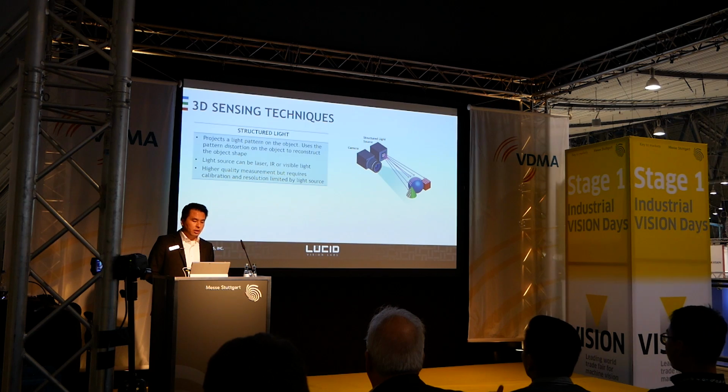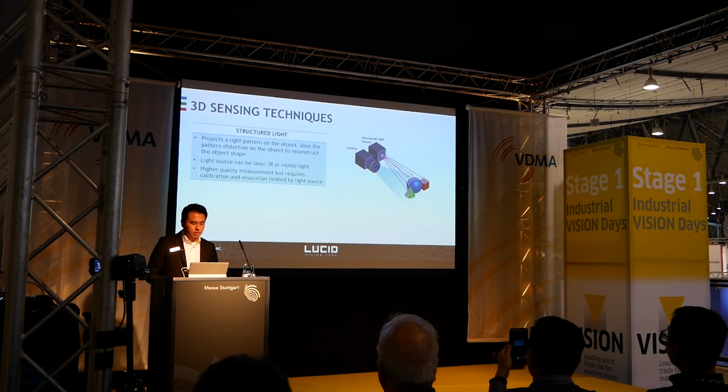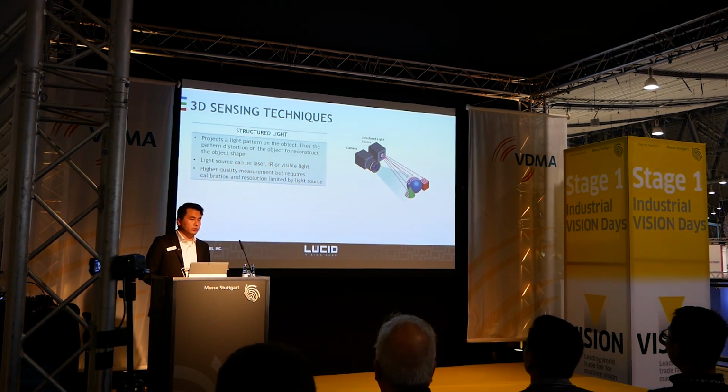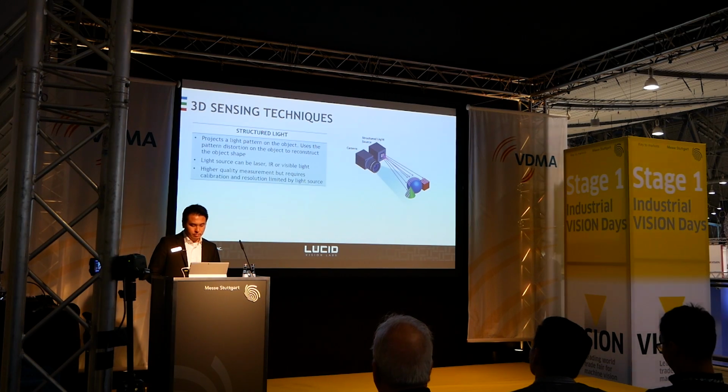So structured light is typically used in higher-end applications like metrology because the accuracy is typically much higher than stereo vision, for example. But the resolution of structured light is limited by the pattern it can project from the projector.